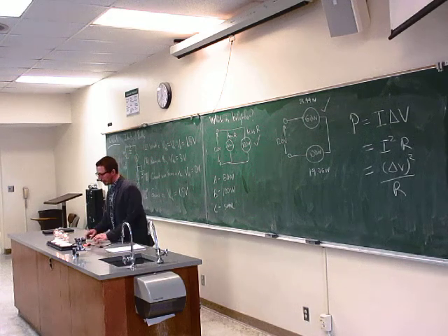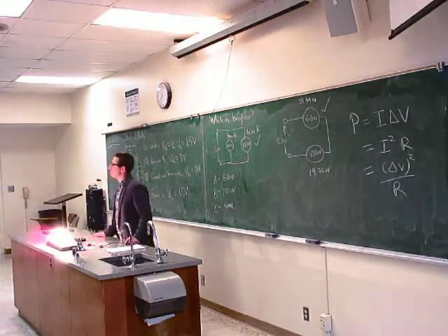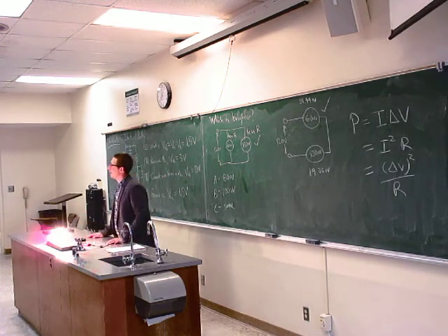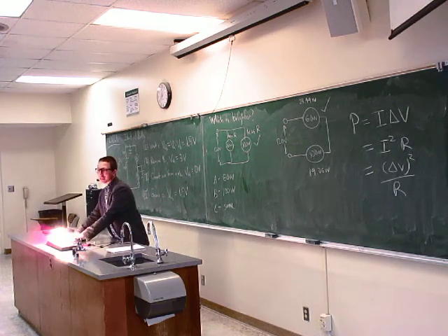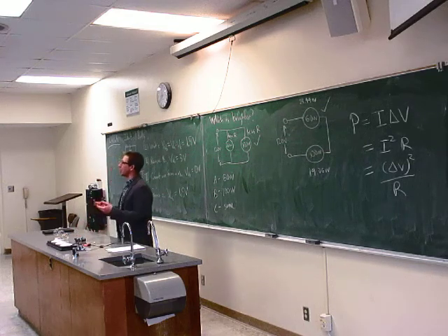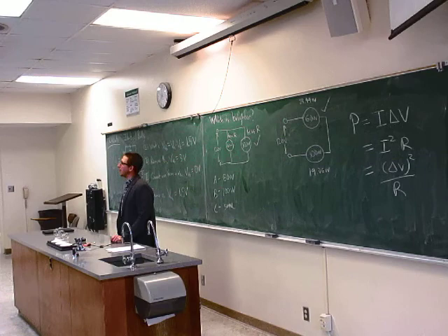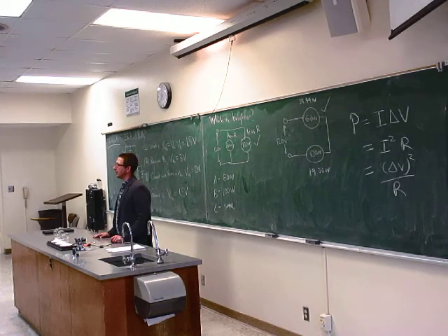They're only going to be dissipating 60 watts if I connect them in parallel. In parallel, this is costing more energy. They're dissipating more energy when connected in parallel because the effective resistance is less. More current is being drawn from the same fixed voltage source, which is coming from, in this case, the outlets. Good question. All right. Any other questions here?